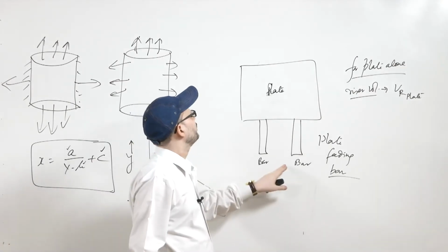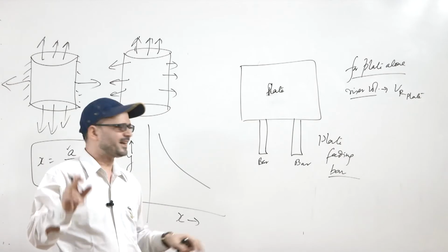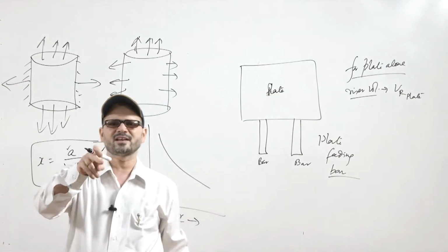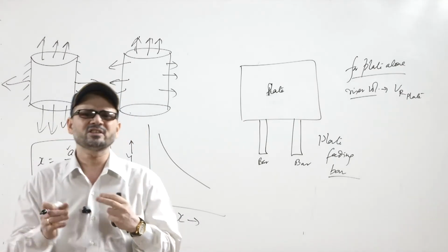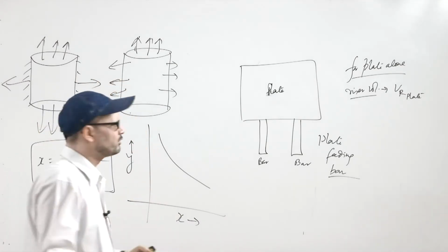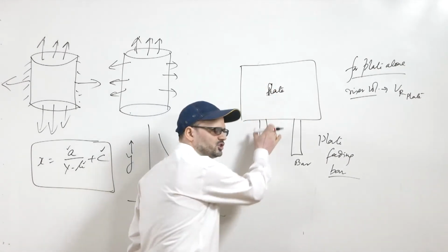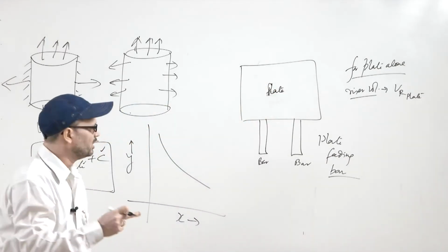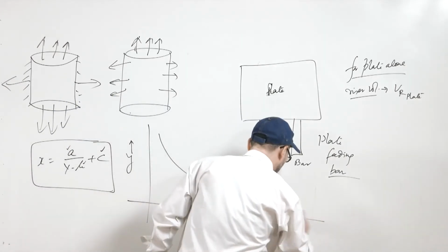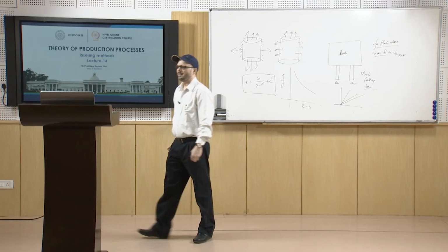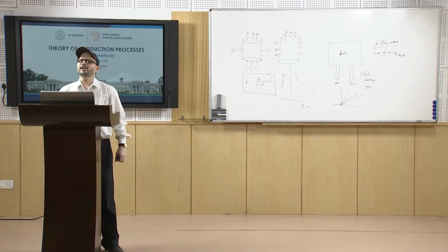You will find the ratio of the thickness of this bar to the thickness of this plate, that is, thickness parasite by thickness parent. Parasite means the appendage which is taking the liquid metal from this main casting. So, you will have the thickness ratio. Once you have it, you go to the typical curves, as you see. This is a case of plate feeding bar.